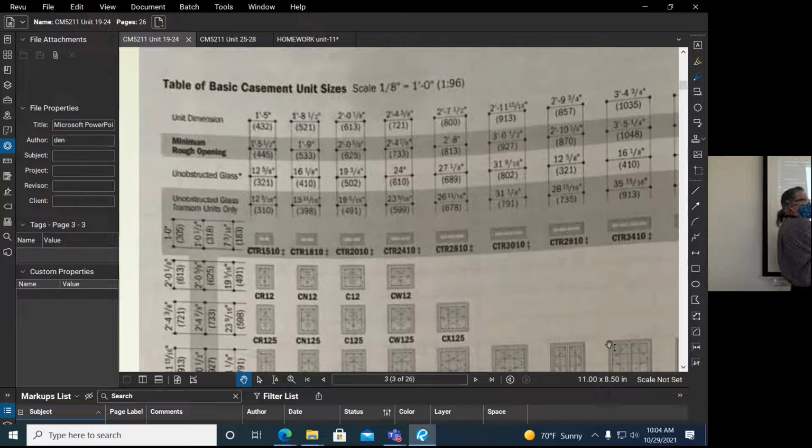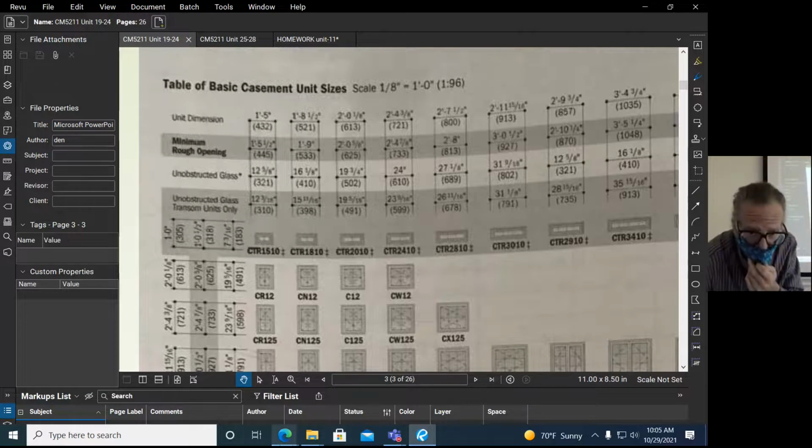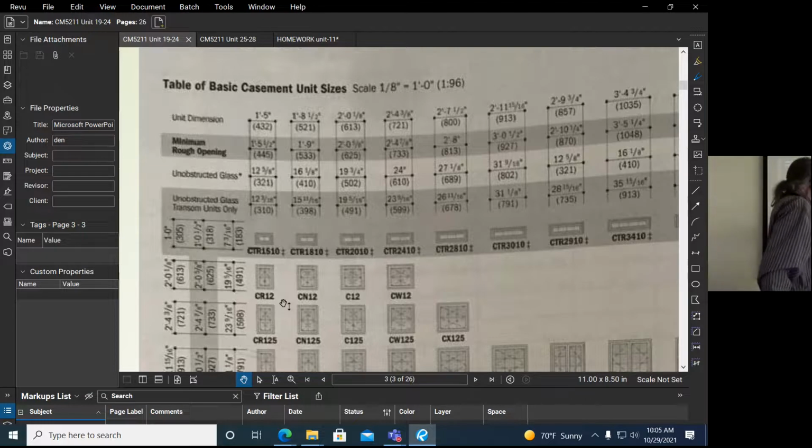The actual size of the window is bigger, and it's bigger because the framing is larger, and you want to have that size of a window open. So the window frame has to go on the outside of that to hold all the glass and hold the hardware and all the elements of that. So what we need to know for framing from the cut sheet here is how big to make our rough opening in the building. So that's this column, this row right here. And then the column that shows you the rough opening is, so the rough opening this way is shown along the side here.